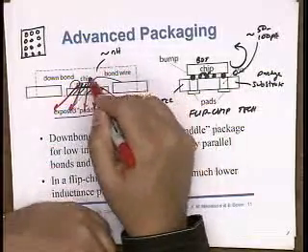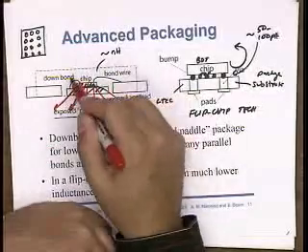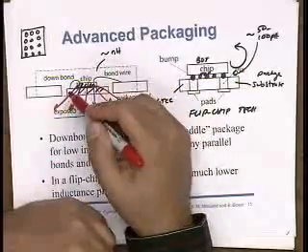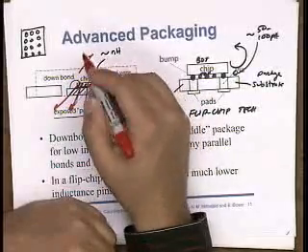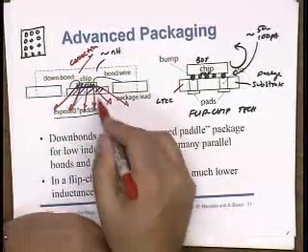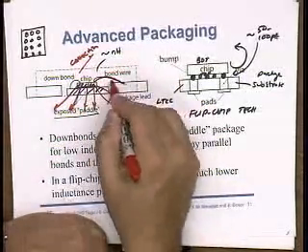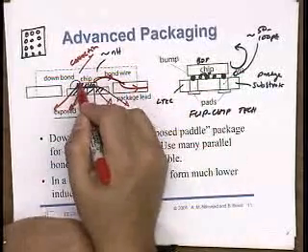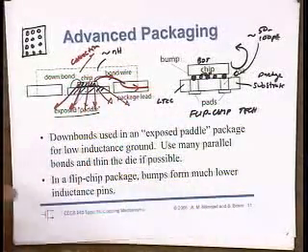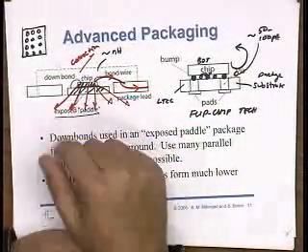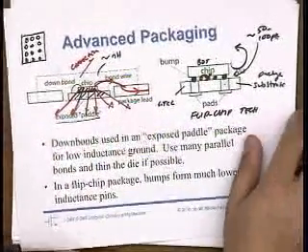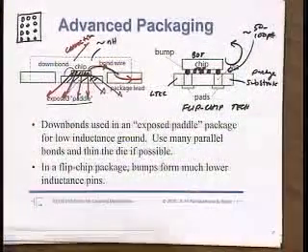This is usually covered up, and the plastic on top is not as good a thermal conductor, so there's not as much convection. There's some convection, and there's mostly conduction. So most of the heat is being removed through conduction. Some of it is also being removed through these wires, but most of it is going through this bulk substrate. The substrate is physically large, and this package is also physically large, so this acts like a good heat sink and pulls out the heat.